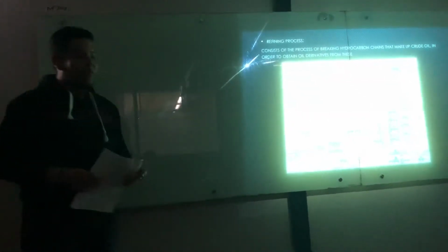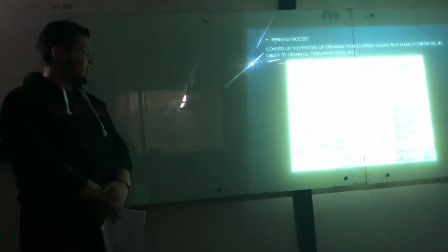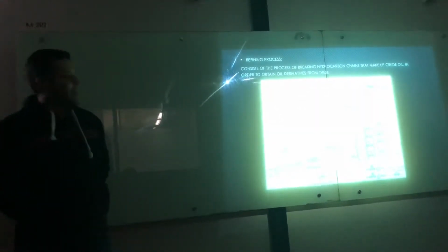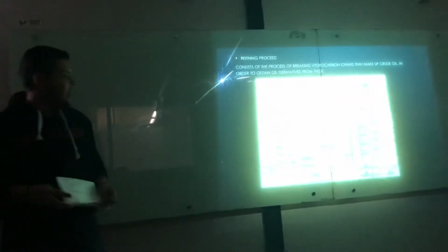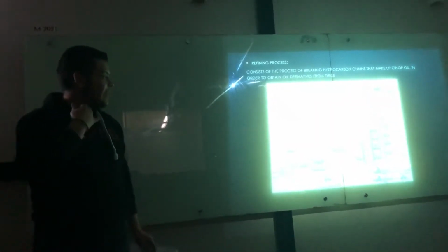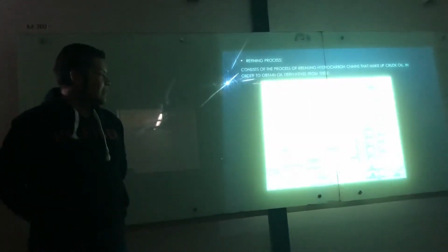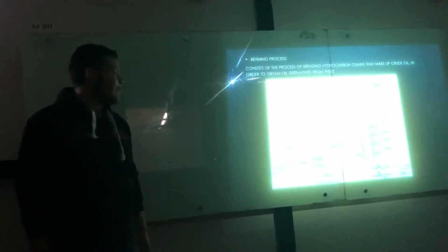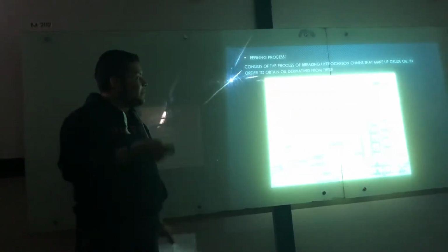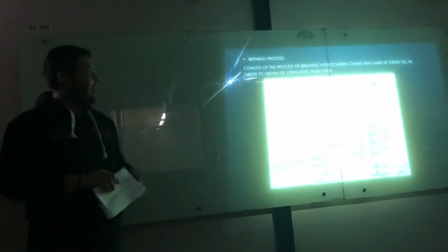In the first point, the crude is pumped to the first heat exchanger, where the preheating process is carried out. In point number 2 of the diagram, we have a desalter, and in this part, the salt in the crude is eliminated. And at the third point of the diagram, we have the other heat exchanger, and in this part the crude passes through the heat exchanger and is partially evaporated. And after that, the crude goes to the evaporation column.